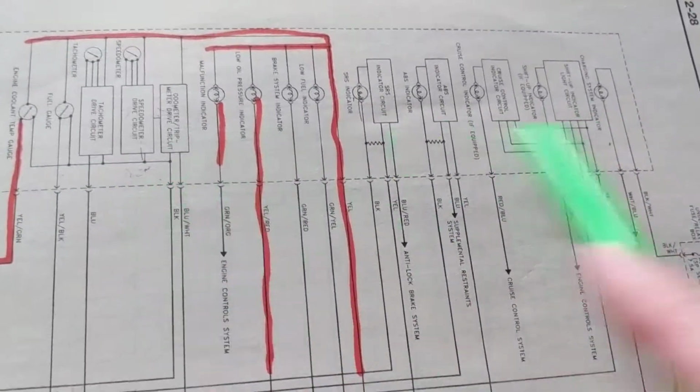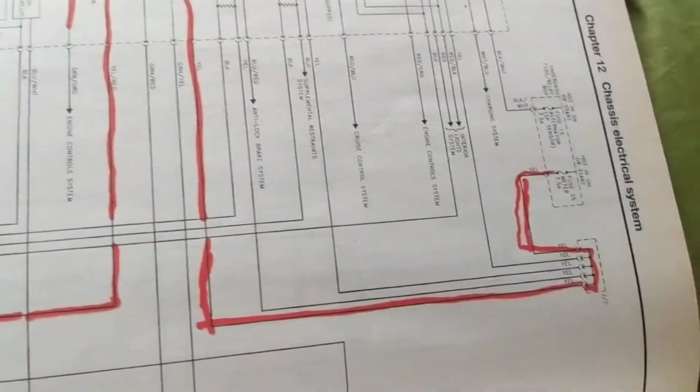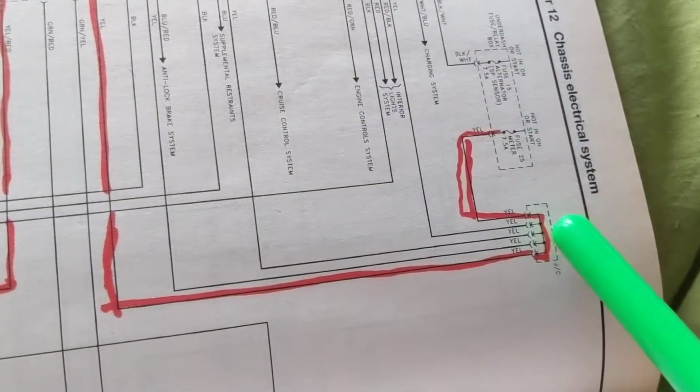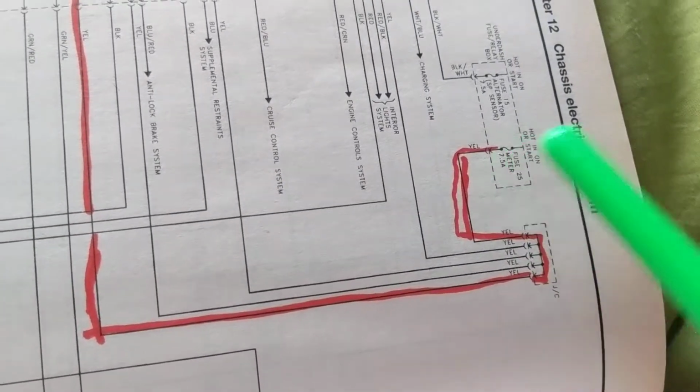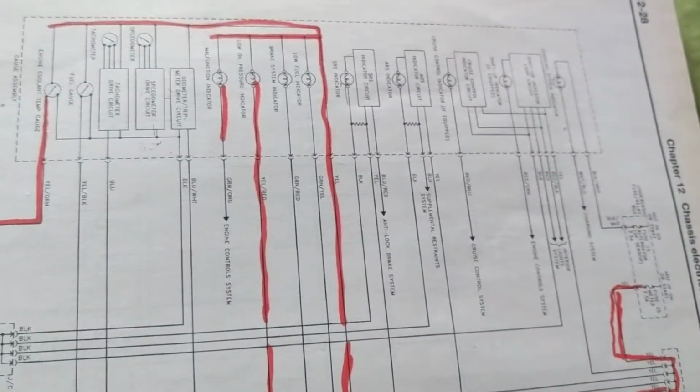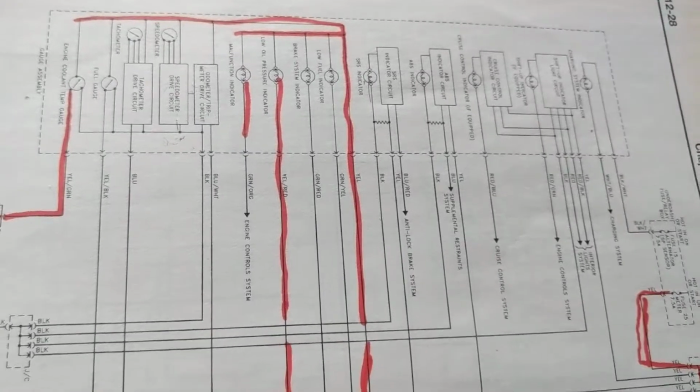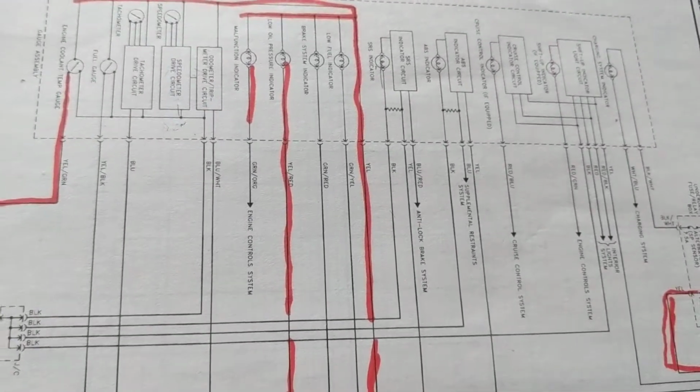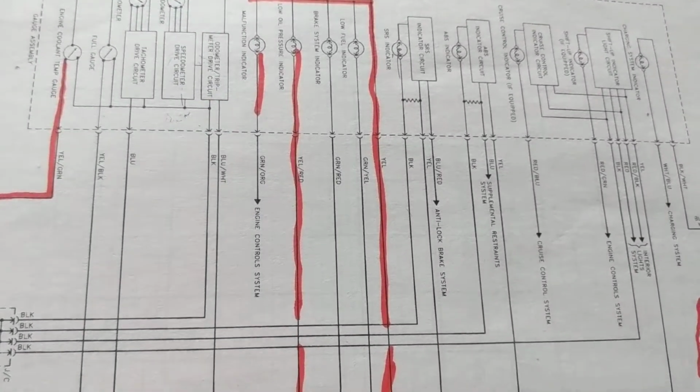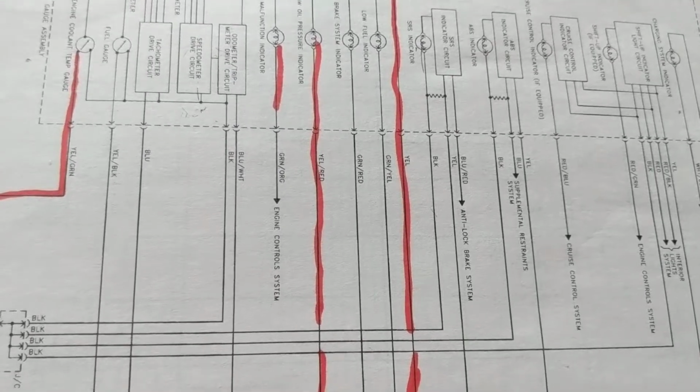Okay? So, obviously, if all lights do not light and the gauges do not light, what am I missing? I come over here, right? Probably the fuse is not good. Maybe the battery is low, right? If your battery is low, do not expect to turn on the lights or to crank the engine.